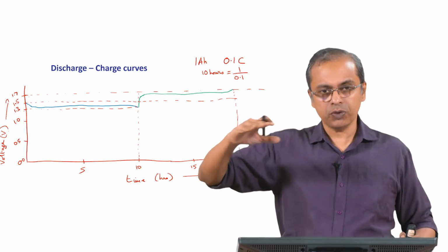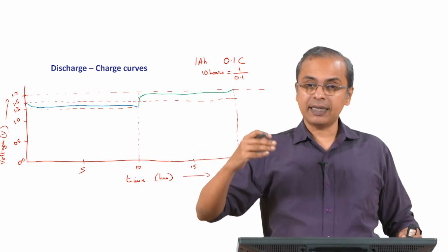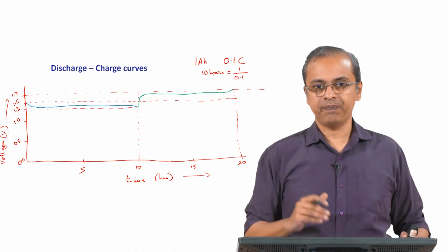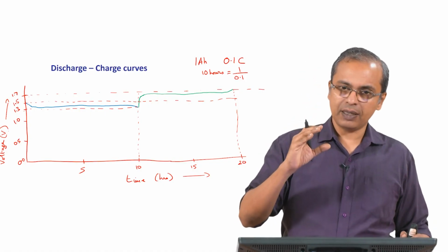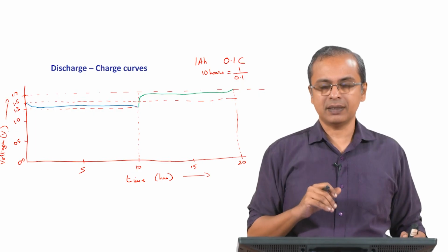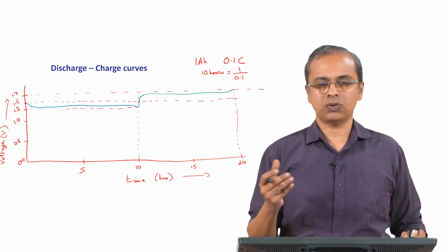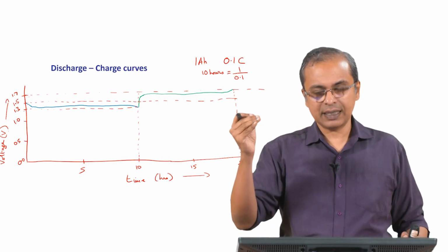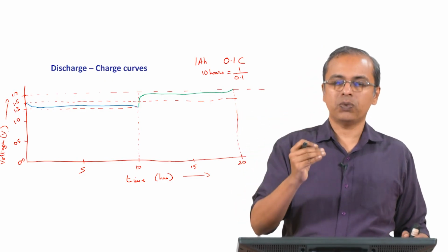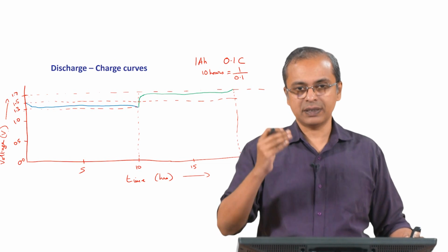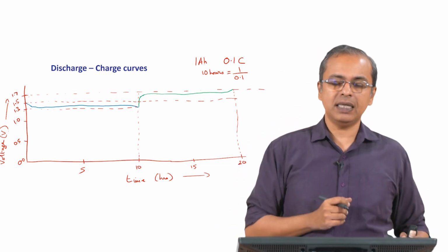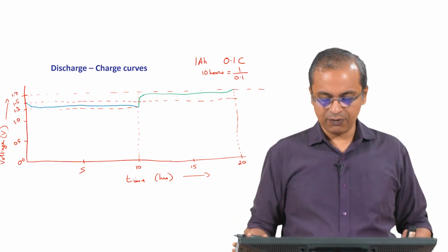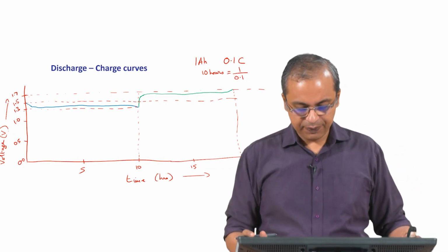At 1.4 volts most of the discharge happens, and then when you do the recharge, most of the recharge is probably happening at 1.6 volts. This is because of various inefficiencies present in the system, including IR resistances and so on. So you end up having to put in more voltage when you recharge the battery, and you get a little less voltage when you discharge it. There is always a gap there that represents the inefficiency; that is what this curve shows you. Okay. So this is how this curve would look.